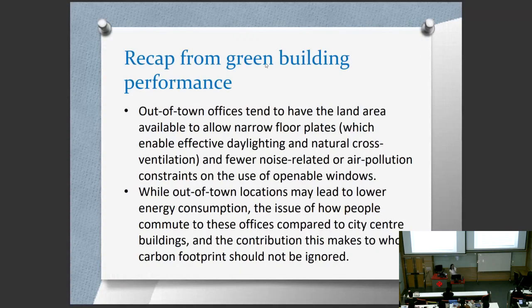Okay, recap from the green building performance. So out of town offices, those far away from the city center, tend to have land area available to allow narrow floor plates. Narrow floor plates means that everywhere is close to the window. Okay, so this enables effective daylighting and natural cross ventilation, and there are fewer noise-related or air pollution constraints on the use of openable windows.